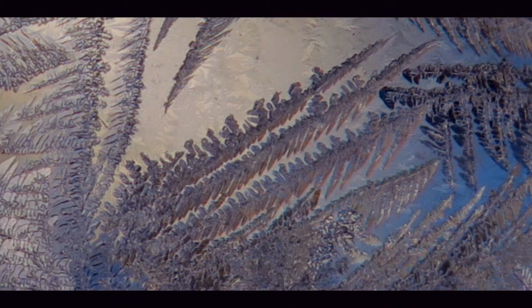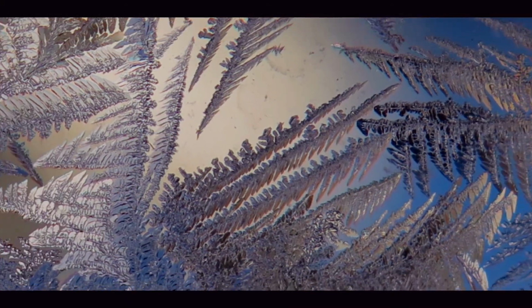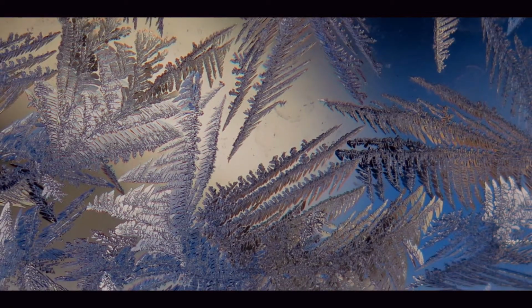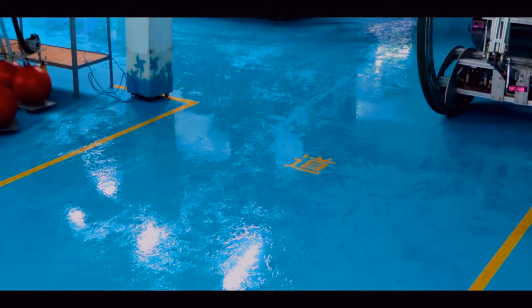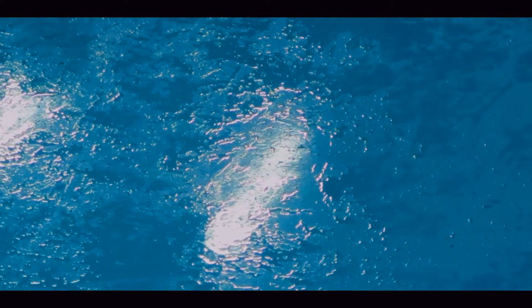Now in Calgary, in northern climates, sometimes what happens is it freezes, and there you can see evidence with frost patterns form, and essentially what's happening is the moisture in the air condenses and then it freezes. This is an example in China where the floor is actually below the dew point of the atmospheric air, and so what happens is you get puddles forming on the floor due to the fact that the floor itself is cooler than the dew point in the air, and you have condensation occurring on the surface.